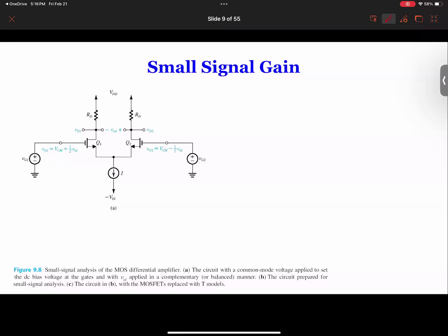So when you do the minus, because if this is positive, they become common mode where the output is 0. That's why you have to have positive here and negative here. So this is negative here. So this is negative. When you get the output, this is negative minus this positive. This will give you the same gain.